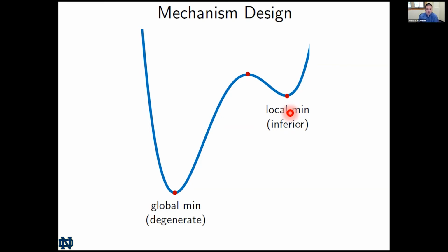And so what we want to do is we want to use homotopy continuation to explore the trajectories along here. So we have actual paths now between, say, saddle points and this global minimum that we can now track along and actually use those in our designs. We don't have to be just looking at local minima. We can look at whole paths in between them and construct mechanisms from there.